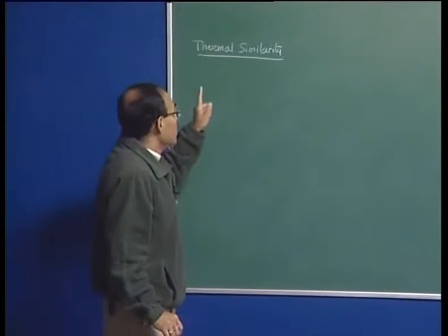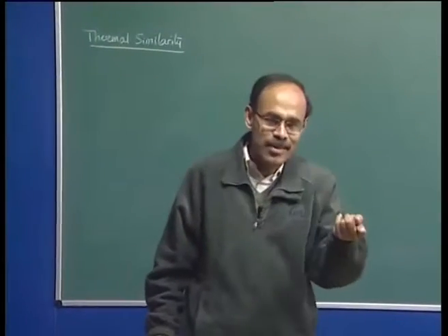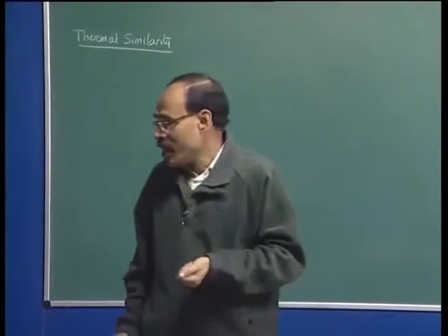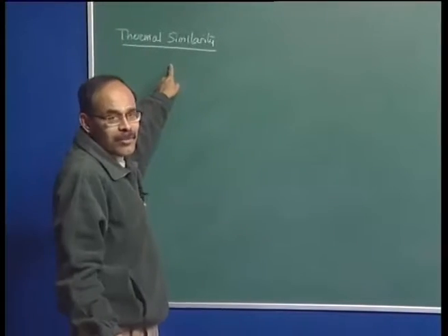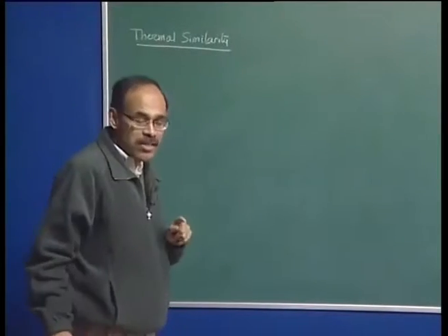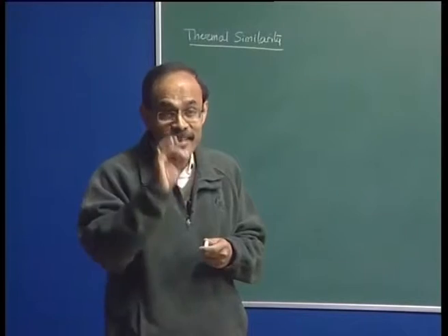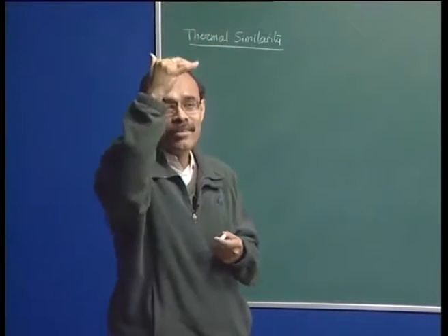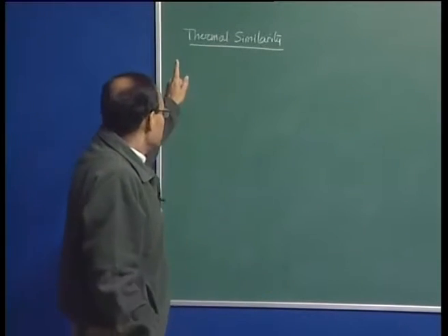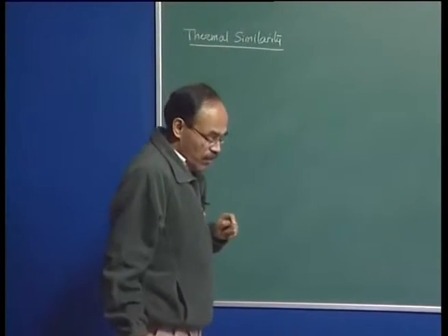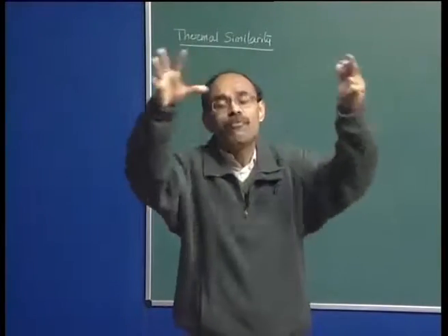Now, before we can satisfy thermal similarity, we must understand that we have to address mechanical similarity or dynamic similarity. Unless we can talk about the similarities of fluid motion in the system, we cannot talk about thermal similarities. So, that is why when I started talking first about modeling and measurements and outlined the 4 states of similarity, I did mention that the order is very important. Geometric similarity, then dynamic similarity, then thermal similarity, because if you do not address dynamic similarity, we will not have similarity of the flow patterns or similarity of flows in the system.